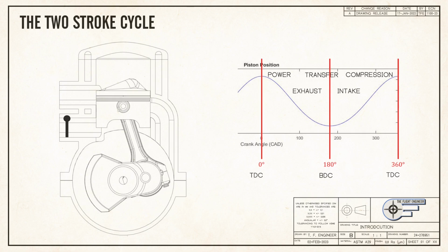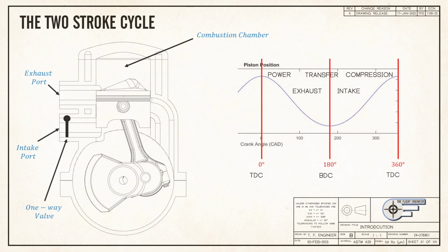Two-stroke engines are somehow much simpler and simultaneously more complex than a four-stroke. They are often mechanically simpler, using cylinder ports rather than a traditional poppet-style valvetrain. However, their operation can be complex, as the steps that constitute the combustion cycle seemingly happen on top of one another. To begin to understand this cycle, we'll focus on the interactions in the combustion chamber, at the exhaust port, at the intake port with its one-way valve, inside the transfer port, and in the lower crankcase.